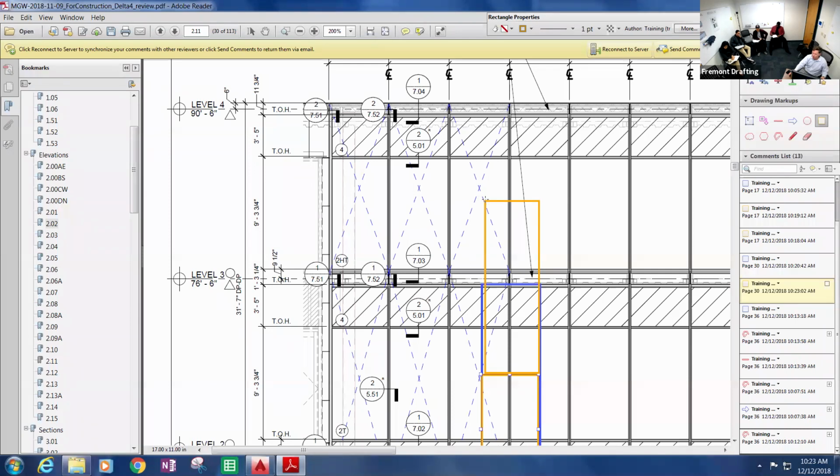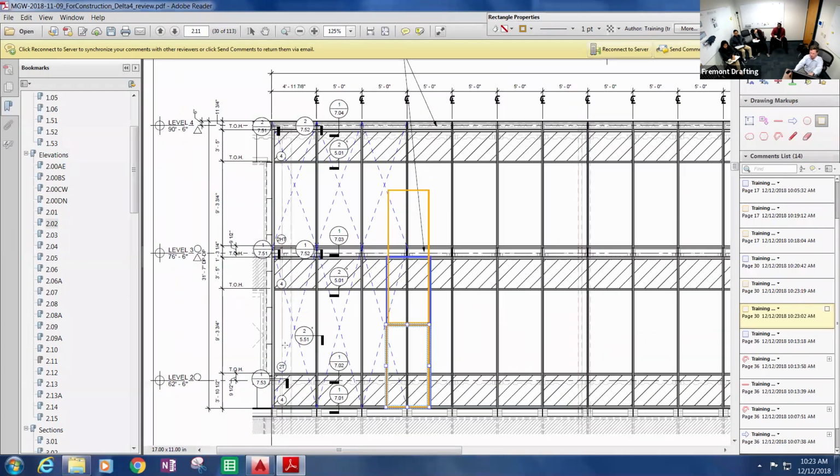And then the wind load for this anchor is actually going to come up like this, because it's catching the other half of that lower unit, but it's also catching the wind load of the bottom half. And so it's really catching 4 corners. It's catching 1, 2, 3, 4. So it's really catching a fourth of the load from 4 different units, but it really just comes back to being 1. So typically, the way we determine our tributary area is by the bay width, 5 feet, by the height, 14 foot.